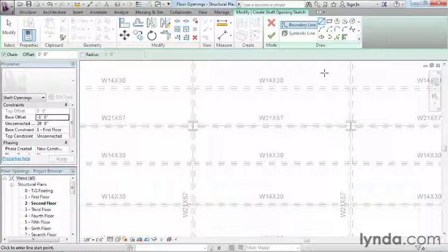Now I happen to know that this starts off about 1 foot off of where this beam is placed. So in order to do this, we'll start off by using the line work tool, but we're going to set an offset value. So when we start to draw, it's going to place this first line 1 foot away from where we're drawing. We'll select offset 1 foot, pick the beginning spot for where this line should be, and then move straight down.